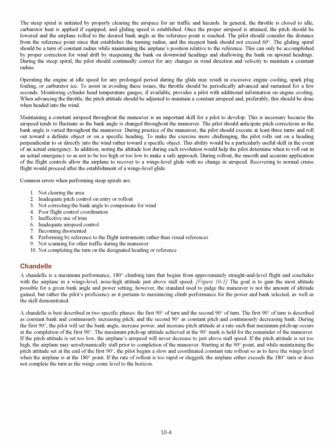6. Inadequate airspeed control. 7. Becoming disoriented. 8. Performing by reference to the flight instruments rather than visual references. 9. Not scanning for other traffic during the maneuver. 10. Not completing the turn on the designated heading or reference.